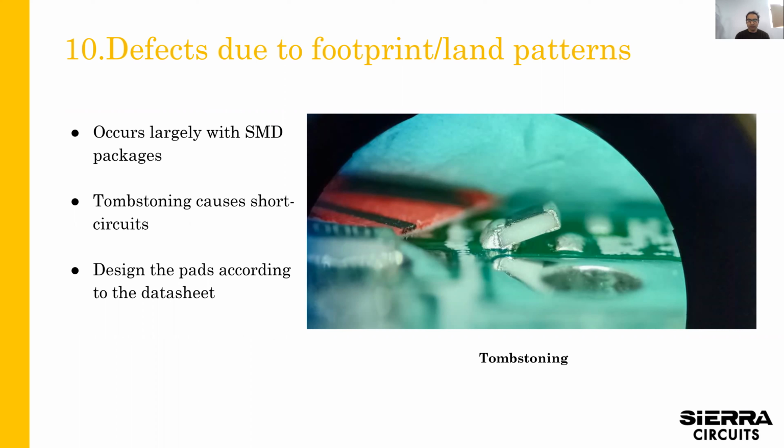So if you have too much solder or bad solder paste accuracy and deposition, you can have all these sorts of issues. But from a designer's perspective, the way you control this is designing your pads properly and then also designing your solder paste layer properly.